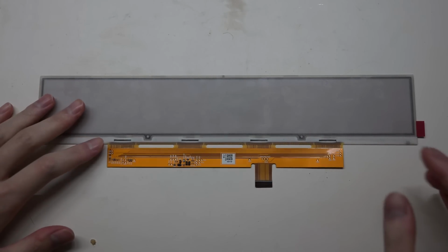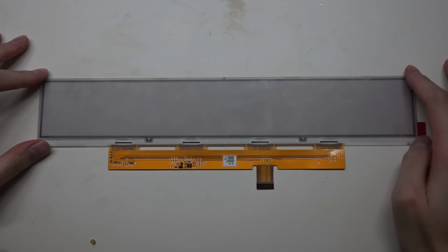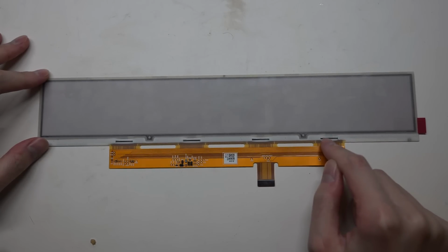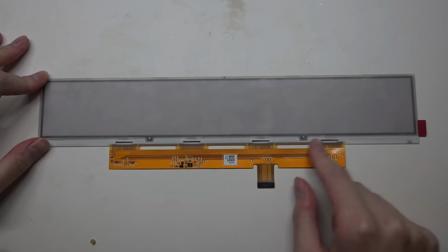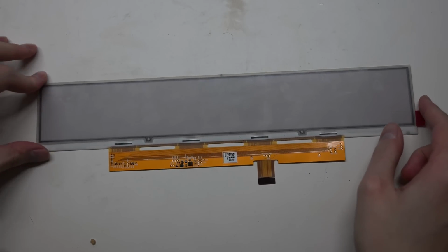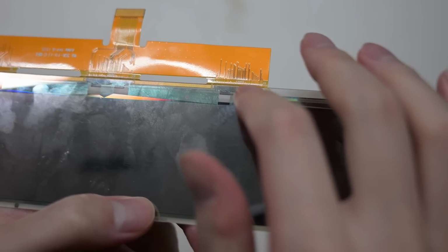If I know how this chip is connected on the glass substrate, and I know the pinout of these tiny chips, I can follow the trace from here, go to here and know the pinout. Then how about on the glass? If I just look at the glass, I can see these traces. It will be kind of trivial to trace through these glass wires, these ITO wires on the glass.